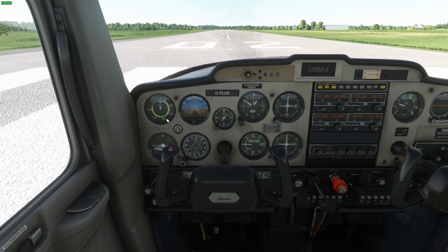Airspeed, cruising at 100, take off at 60, and climb and descent between 70 and 80, depending on flap setting and airplane loading. Stall speed is down into the 50s, so we don't want to go there. The wings will stop flying, which is very dangerous.